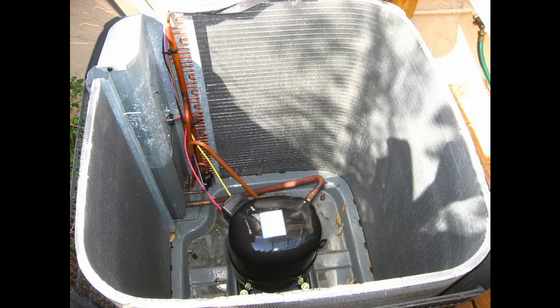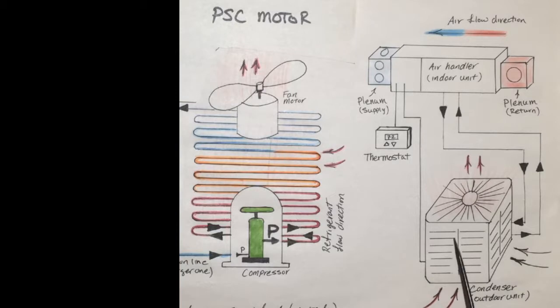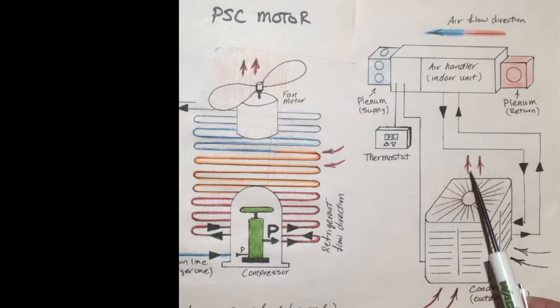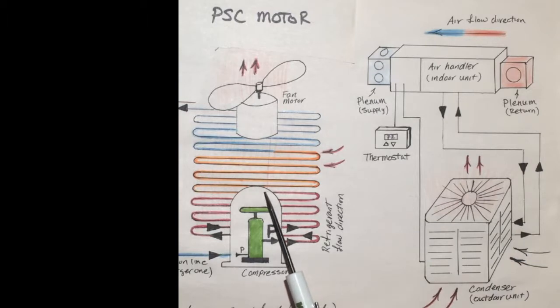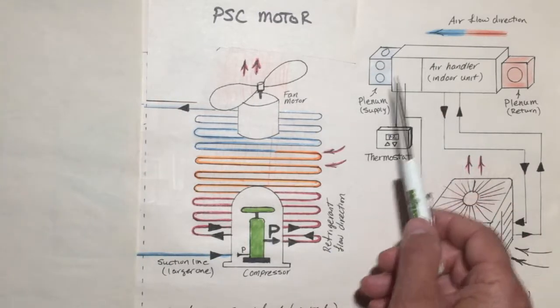There's a little gap over here where our electrical components sit, but almost a 360 degree wraparound that pulls this air in. As it's pulling the air in, we're cooling the refrigerant and taking that heat that we've captured from the inside and release it to the outside. Okay, so now let's take a look and see what's on the inside of our conditioned space.